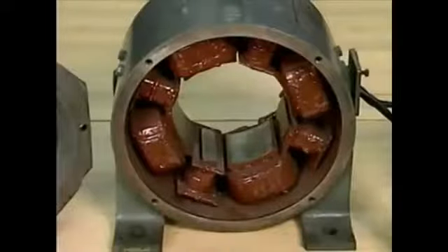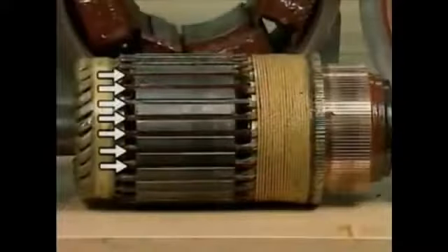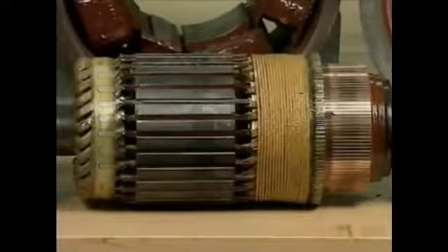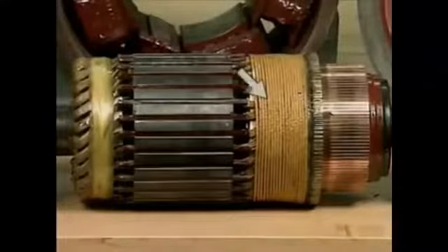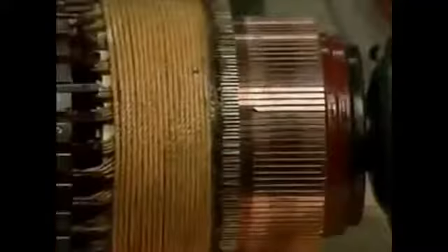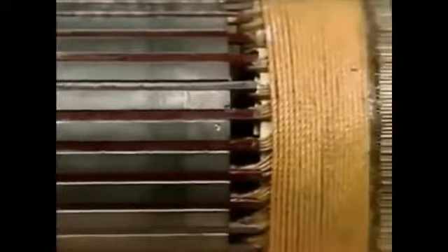The stator is made of coils of wire that are wrapped around iron cores. The coils are electrically connected to a DC power source. The armature contains several loops of wire that are wound back and forth. All of the loops make an electrical connection to the motor's commutator segments. The electrical connections to the commutator segments are protected and held in place under a wrapping of varnish-coated fibers. Current flows from one commutator segment through the armature and back through another commutator segment.